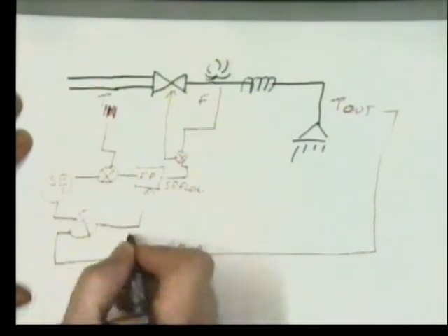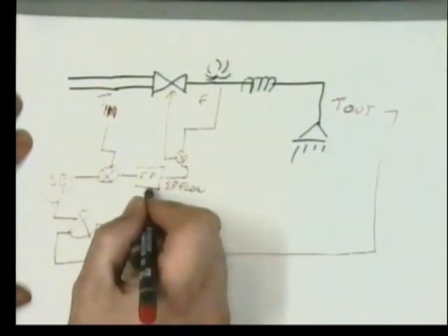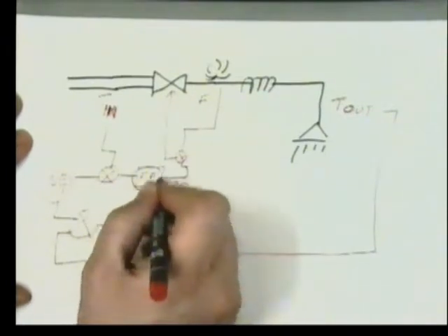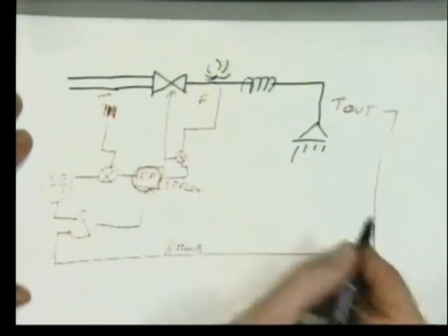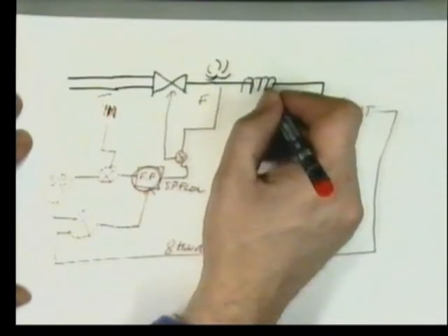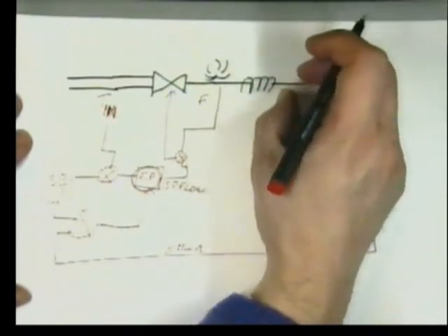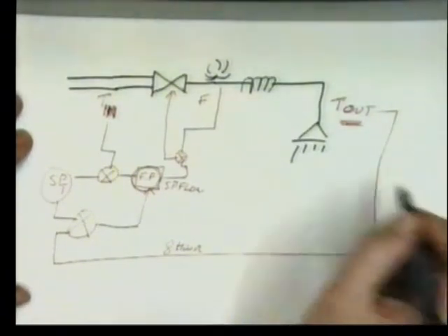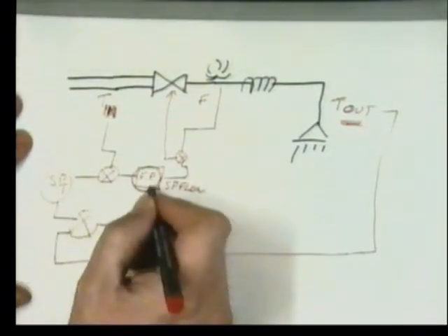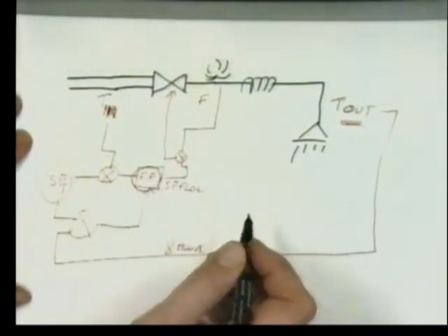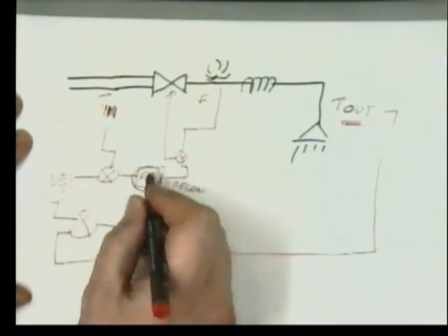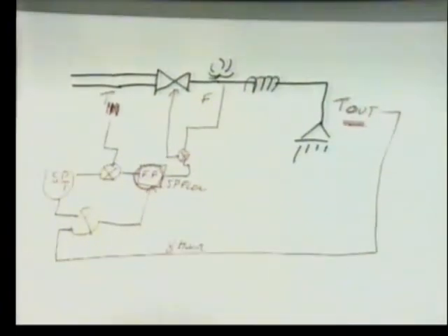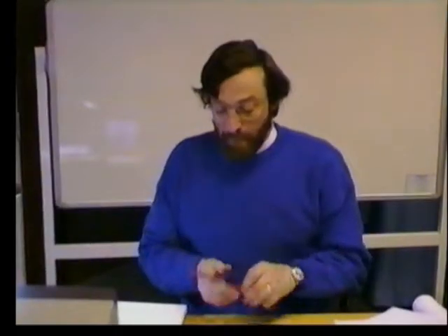This goes on throughout the day, and that dynamically adjusts the algorithm inside the feed-forward model, so that if the heating element deteriorates or a pipe distorts or furs up, we will notice that trend over the day, and we'll feed that back in to our microcomputer, and we will adjust our algorithm to take account of the changing long-term drift. So what have we learned?